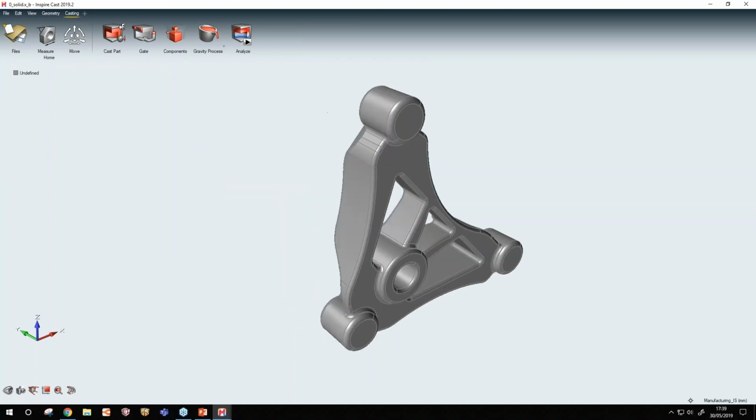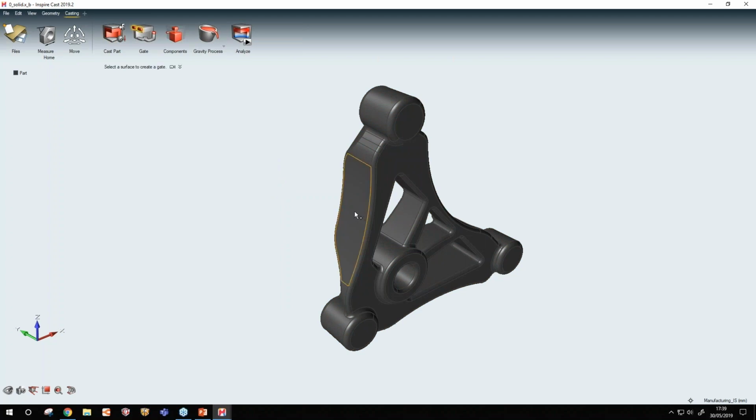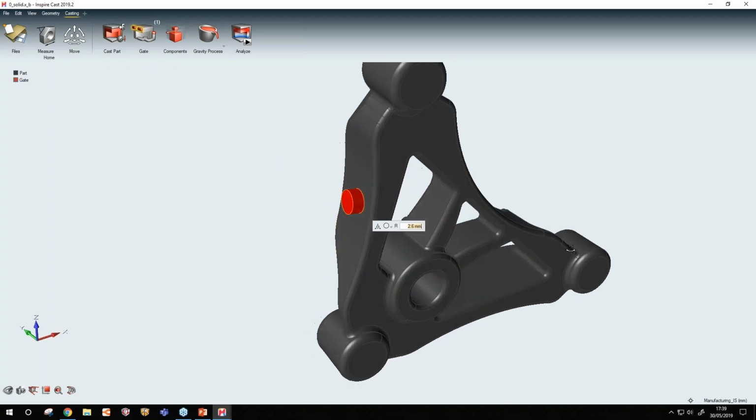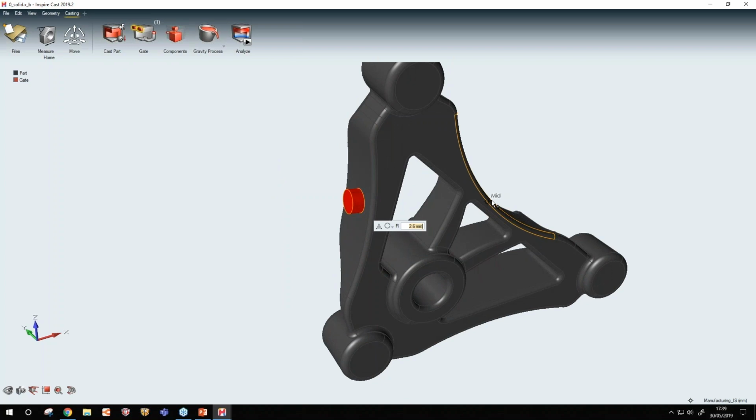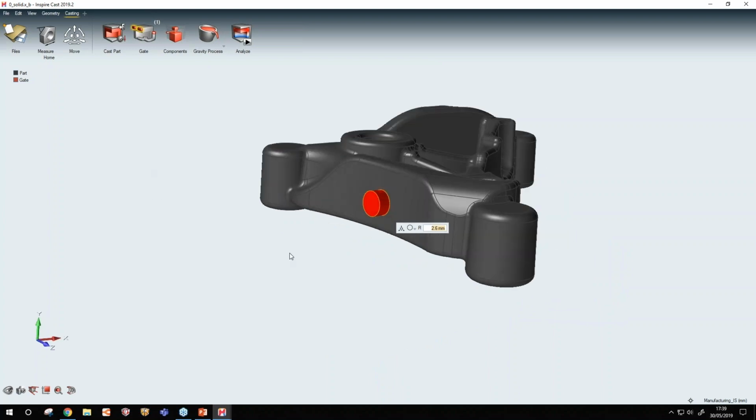So we can have two situations. One situation is when we have only the gate, that is representing the latest portion of the runner. In this case, we need to define the velocity that we consider will get the material on the runner, at the end of the runner. In high pressure die casting, for example, it's easy to set up because at the end we are designing the full runner to have 30 meters per second or 25 meters per second. But there's no maximum velocity. It depends on your process and the process control you are using.